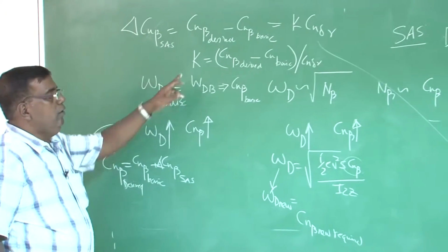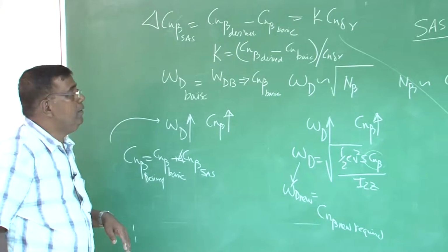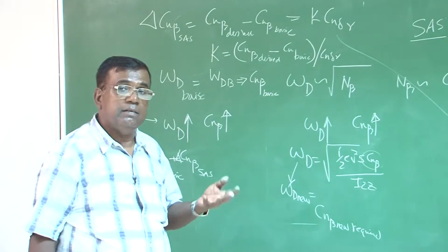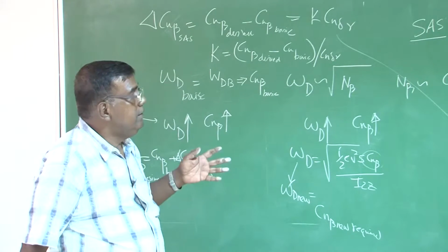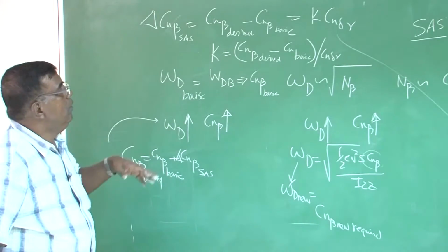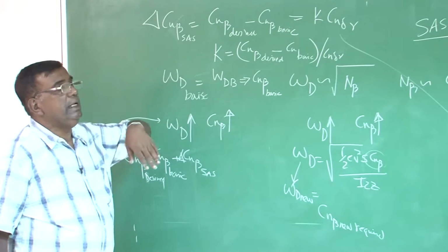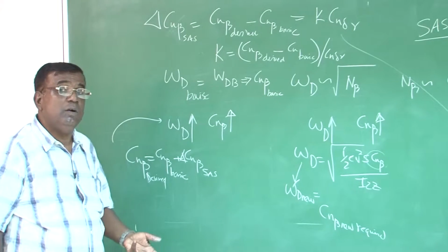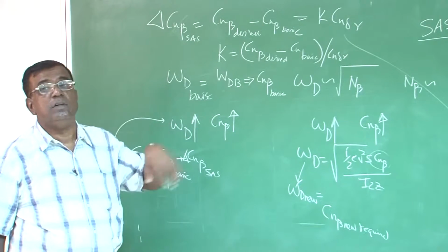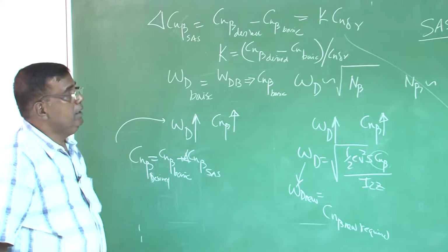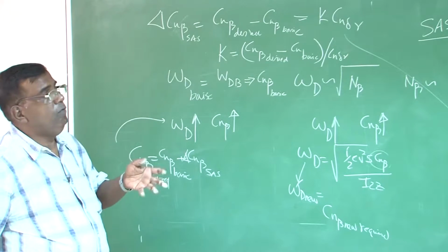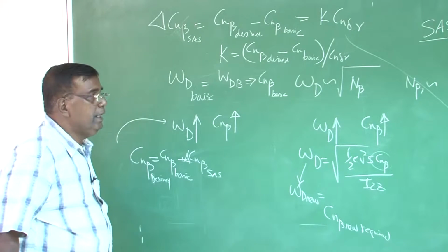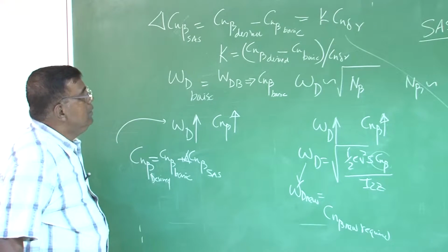So I know what value of k is required, but always remember, if k is too high, it may make the system unstable. So that is why I always say, whatever value comes, you have to go back to the As^4 plus Bs^3 plus Cs^2 plus Ds plus E equal to 0 and see where the roots are lying, right? Especially those who will be working on control, you'll find this is done routinely, although there are shortcut ways of getting some first information.